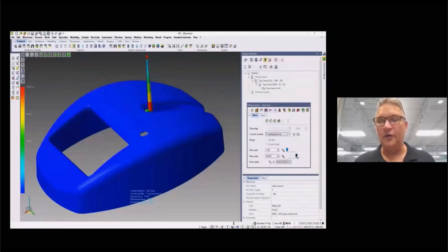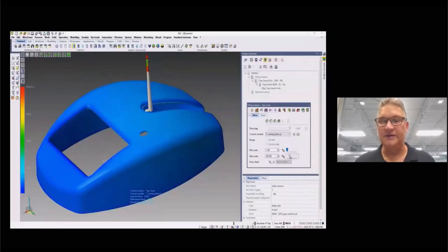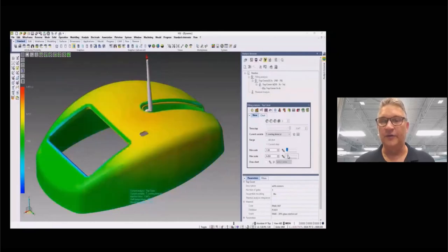With the analysis of the holding phase, we can predict cycle times based on cooling times. This is informative when calculating another analysis. It is very important to understand the cooling time of any area on the part. For example, by adjusting the scale, you can see the cooling times graphically and compared to your original settings to make some decisions.